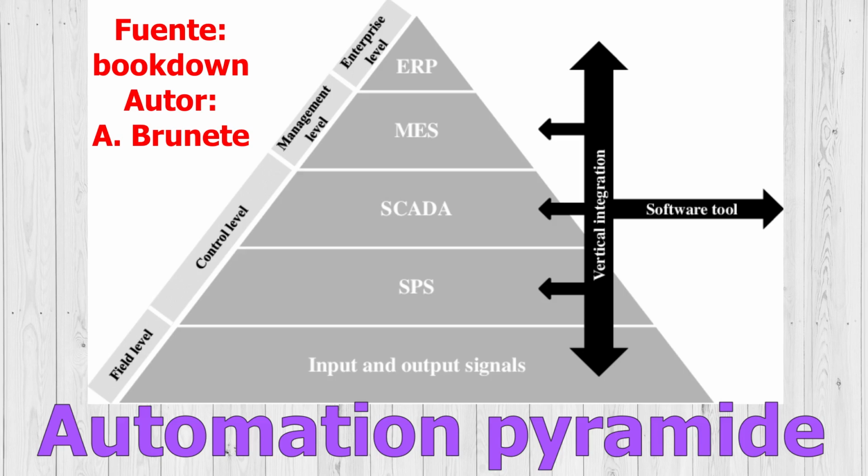The technologies are related to each other, both within each level and between the 5 levels through different industrial communication standards. In the first level, called the field level, are the physical devices. For example, actuators and sensors. In the second level, or the control level, are the controlling devices that can be computers, PLCs, PIDs, etc. At the third or supervisory level, SCADA is used to supervise.